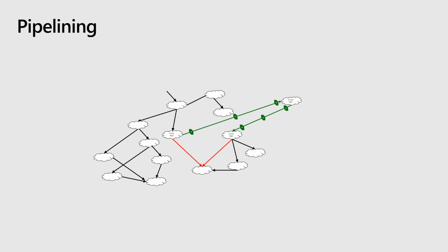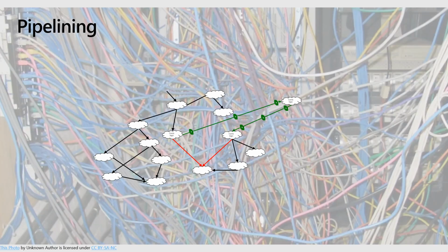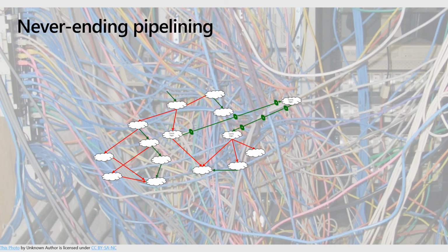Once you fix these 2 red paths that were functionally incorrect as a result of your pipelining on the green paths, that could affect everything else. And so it could eventually cascade to your entire design. And don't forget, this is just one critical path. You've got to rinse and repeat for all the critical paths and iterate this way. It's generally not as bad as I'm making it out to be, but it is very painful, very tedious, and can often result in what I call off-by-n-cycles bugs.